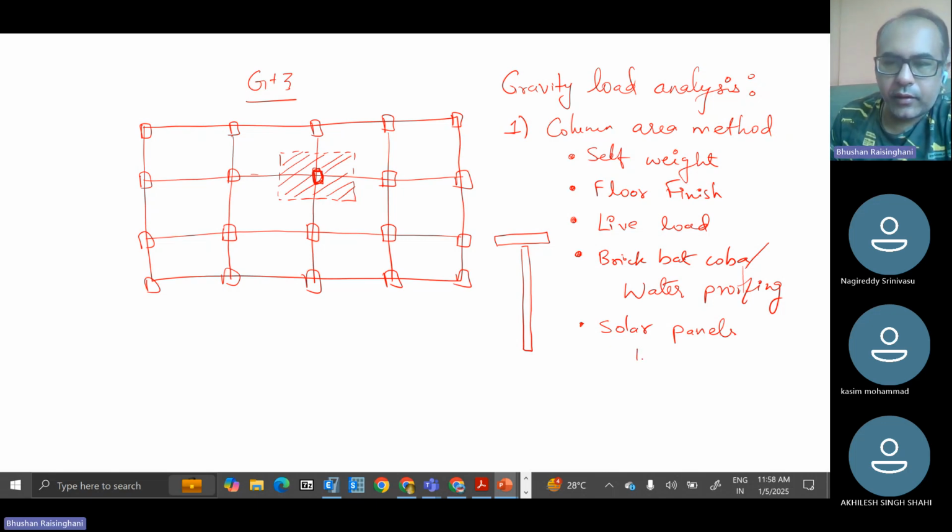So that way, 1.8 meter by, let's say, 2 meter, or 0.5 meter, one panel is there, so there is a weight generally you provide. So many sizes of the solar panels are there. Based on that, you will get the loading from the internet and you can use it. So all these loads will come. This is on the roof.